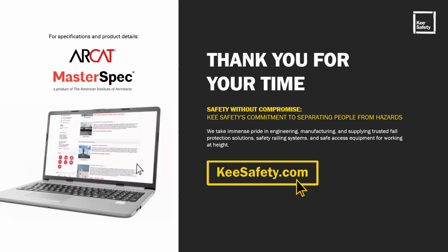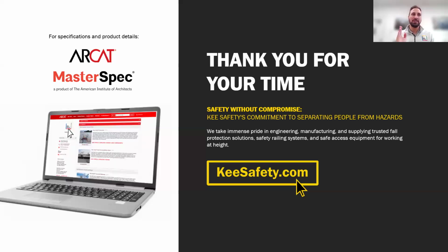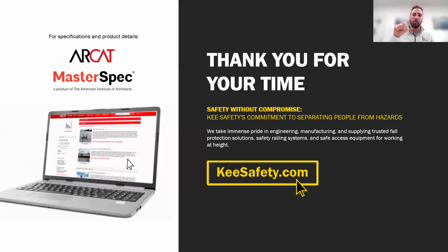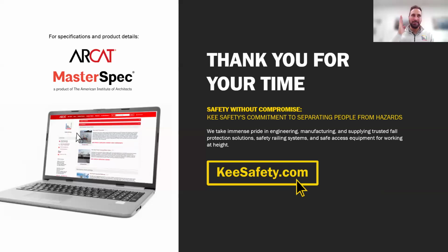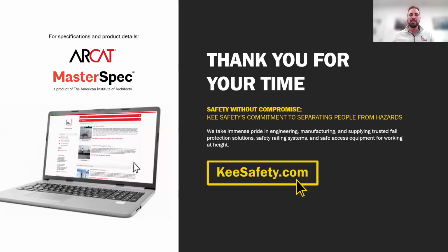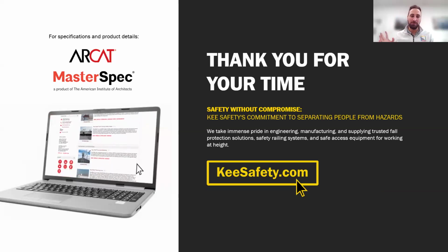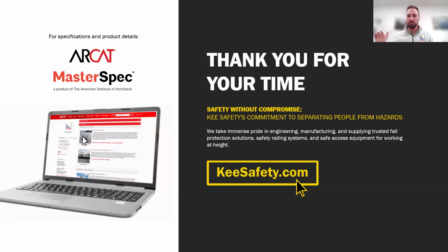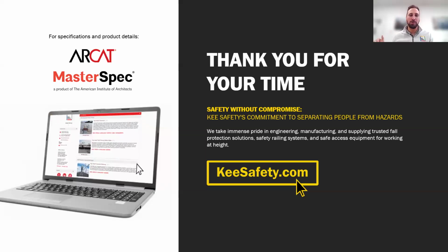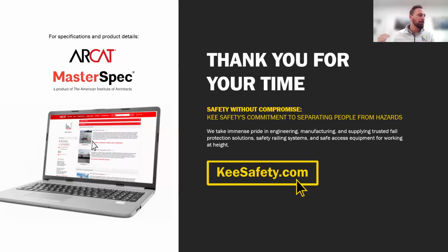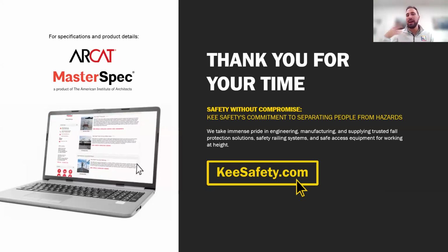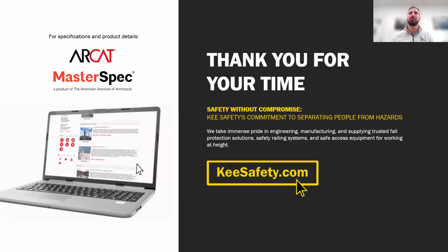That is such a good question because it pinpoints the difference between the original OSHA code and the new OSHA code. The original 1910.23 OSHA code stated for leading edge, any edge 4 feet or more above a lower level must be protected by a full perimeter guardrail. And that was it. Then there were letters of interpretation. Hey, what if I'm 50 feet, 100 feet away from the edge?